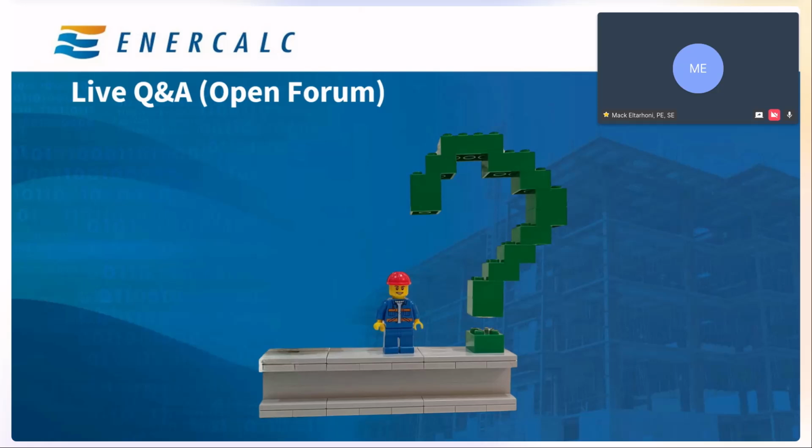And I highly recommend that you take a look at the general beam analysis module. So if you look on the landing page where Mac kept going to add new calculations, under the analysis tools, you have your frame analysis, your 3D finite element, but you also have the general beam analysis module. The general beam analysis module gives you all the same capabilities that you have in the rest of your beam modules, but it's basic analysis. It's not doing code checks or strength checks.